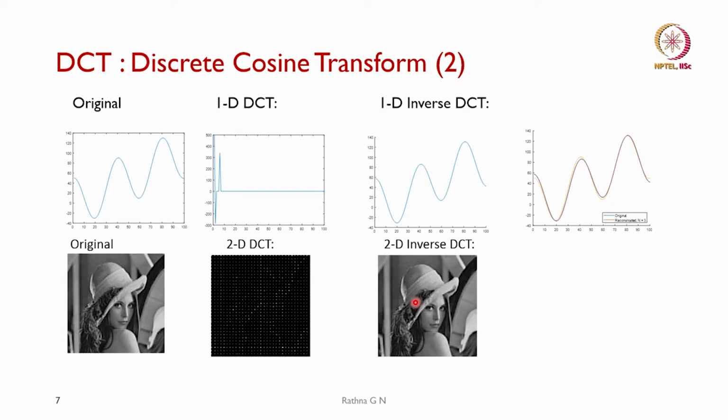The image had 64,000 pixels. From 3,200 to 64,000 the coefficients were made zeros, and only the 0 to 3,200 coefficients were used to reconstruct by using IDCT. We will see these examples in the lab, how we will be doing it.